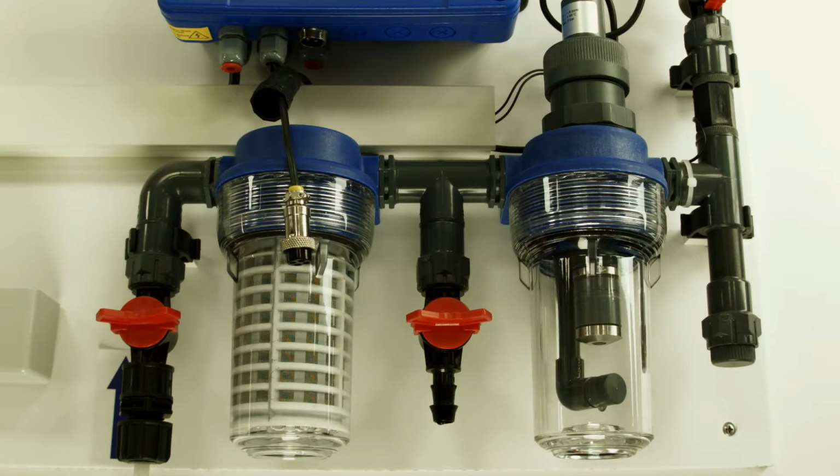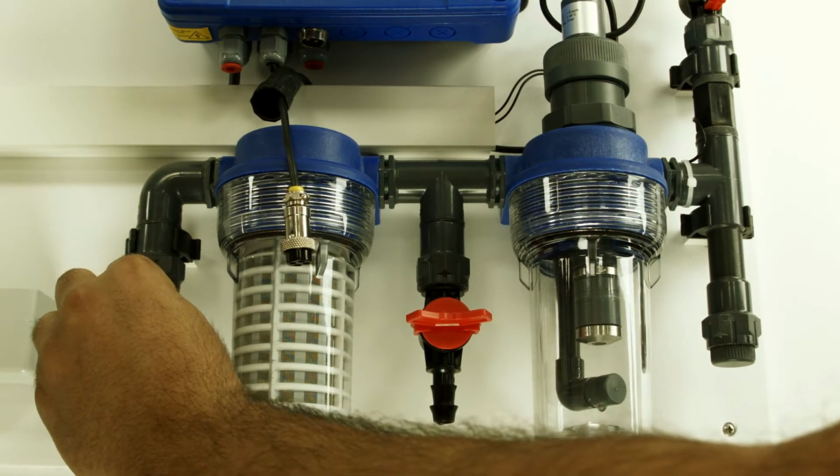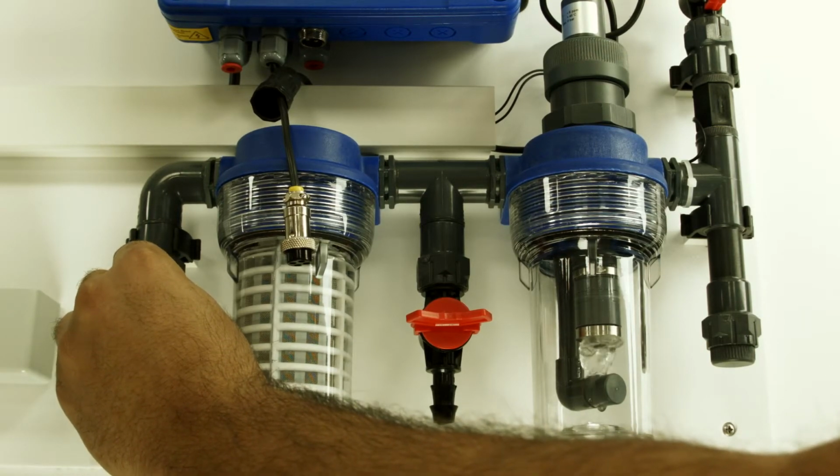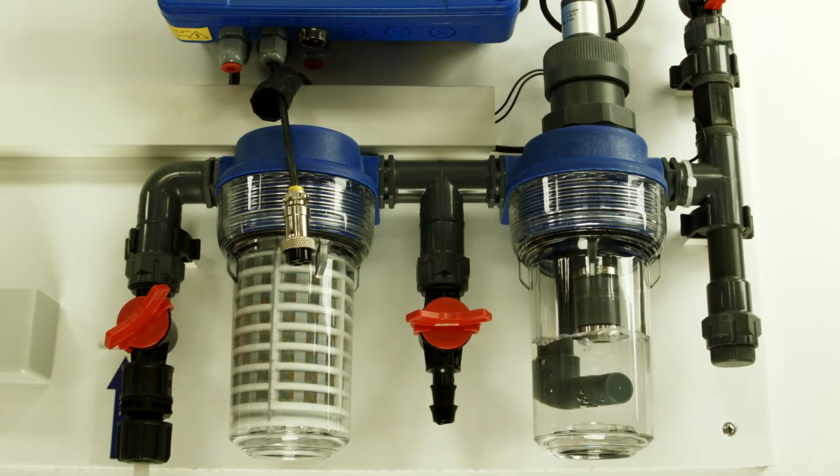There mustn't be pressure in the sample chamber, and the sample outlet should flow directly into an atmospheric drain. Slowly open the water inlet valve after making sure that the water outlet valve is open. Adjust the water flow rate to 30 liters per hour. Make sure there is no air bubble on the sensor tip.